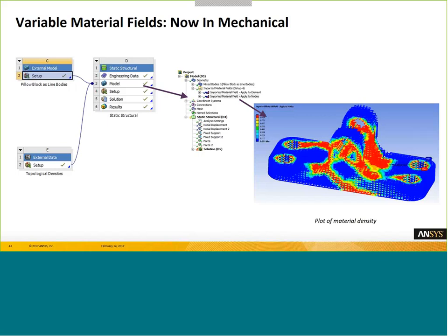So if you're doing things like bone scans, or maybe you're doing something where the material is semi-porous or various steps, like a soil or something, then importing the material properties via external data now allows you to model this within Mechanical. That's a lot more straightforward than trying to wrestle with text files and do some manual mapping yourself. You can do this interactively within Mechanical and visualize it as well to check it's correct. So I think that's really neat.